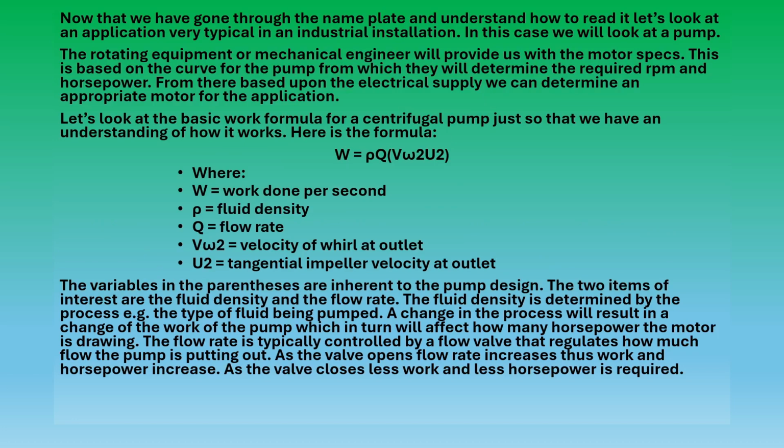Now that we've gone through the nameplate and we understand how to read it, let's look at an application very typical in an industrial installation. In this case, we'll look at a pump. Our rotating equipment or mechanical engineer will provide us with the motor specs. This is based on the curve for the pump from which they will determine the required RPM and horsepower. From there, based upon the electrical supply, we can determine an appropriate motor for the application.